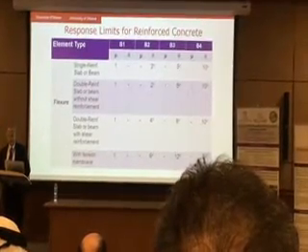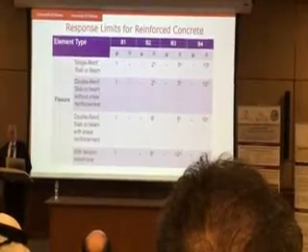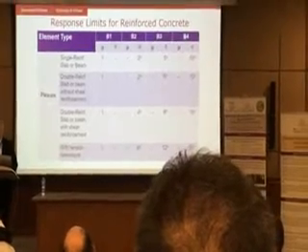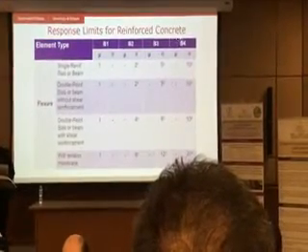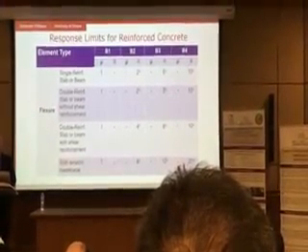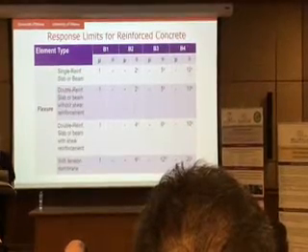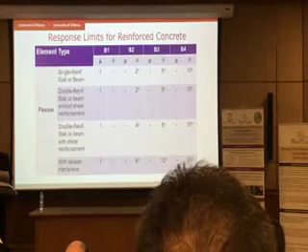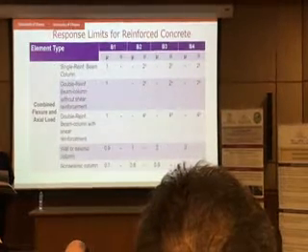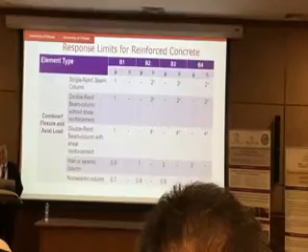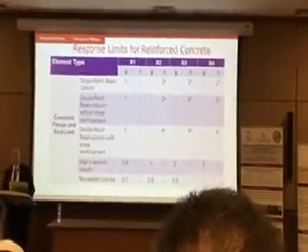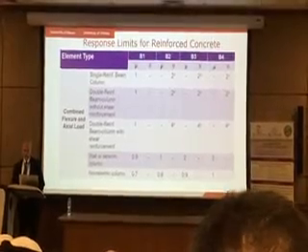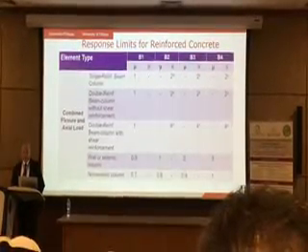So if I'm going to design a building for a very low level of protection, that means I'm interested in B4, so my column has to have a support rotation of 10 degrees. If it exceeds 10 degrees, then it will have to be strengthened. And similarly, the other one was for beams and slabs. This is for flexion axial load, 2 degrees for vertical elements, columns, and walls. And these are the ductility ratios.